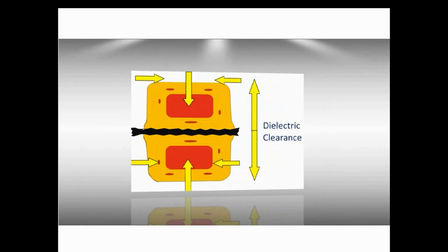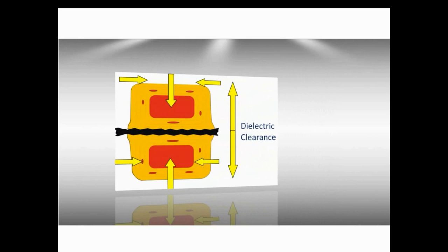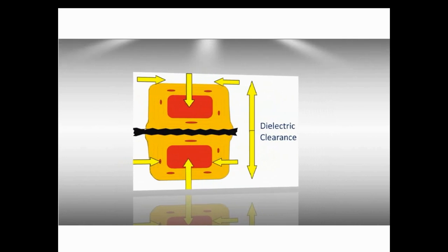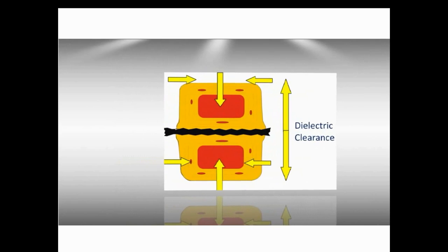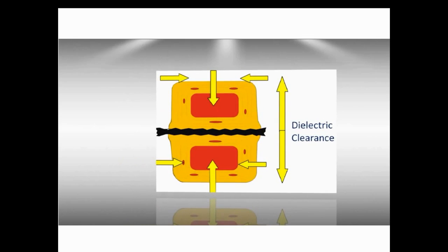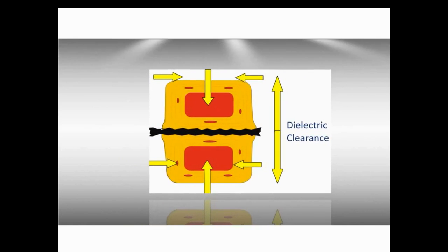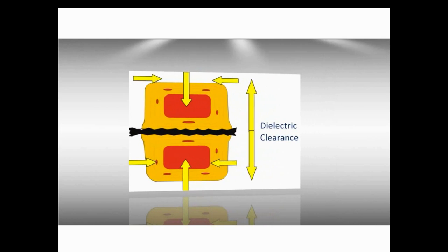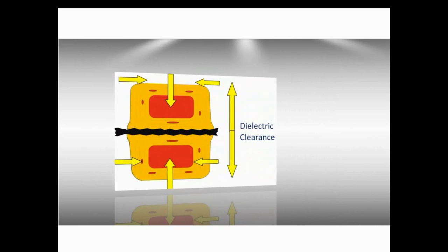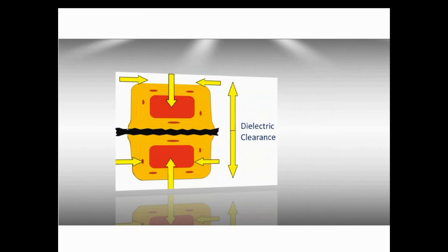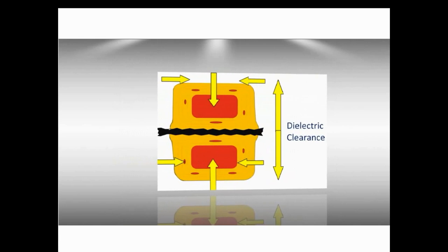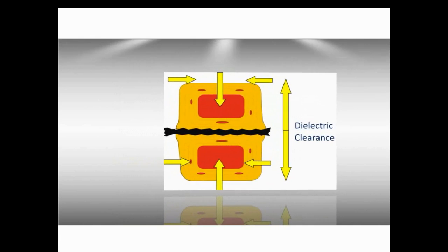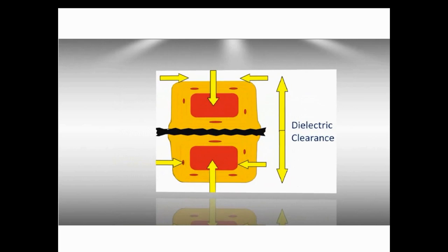And we have come to a question. So, what if a transformer is held together by paper? It can't be under any stress, as it has no moving parts, can it? Other than on-load tap changers and regulating transformers, transformers don't have functional or mechanical moving parts. But a transformer does move as it undergoes vibrations: mechanical vibrations, switching surges, line surges, and limited short circuits.